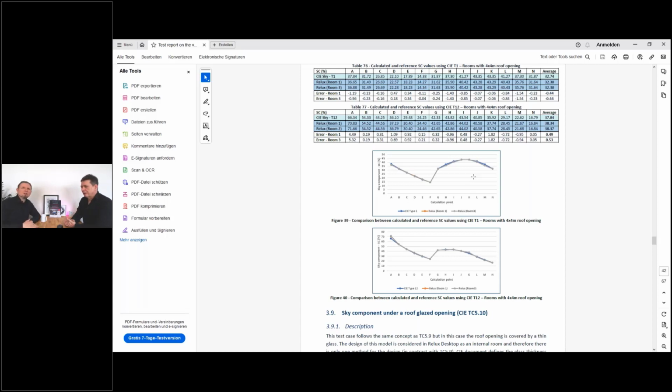We forgot to mention there's also a smaller calculation core for outdoor lighting, more bound to direct parts, and also one for tunnel. Yes, with a bit of indirect parts. Yes, this is the street and tunnel calculation, also related to the photometric law mainly, but it includes a special point which is described in the CIE 140 for the road calculations, the luminance calculation on roads, where we also do not use diffuse reflections.